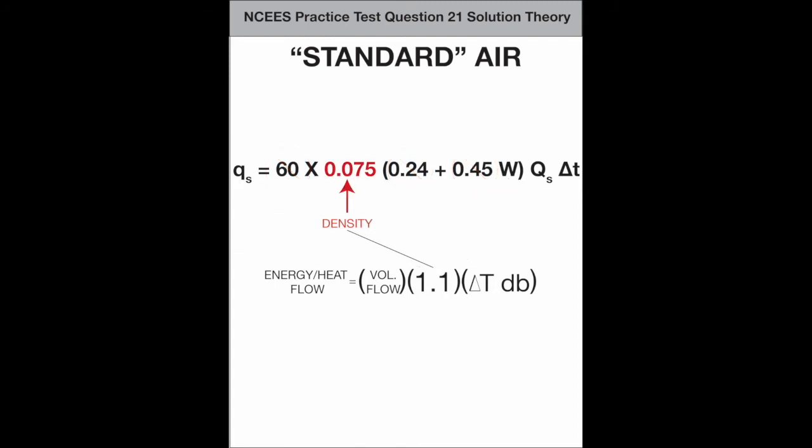Focus on density. As the air changes temperatures, it changes densities. And the change can be quite large. Let that sink in. Standard conditions for air is directly connected with an assumed density and assumed temperature.